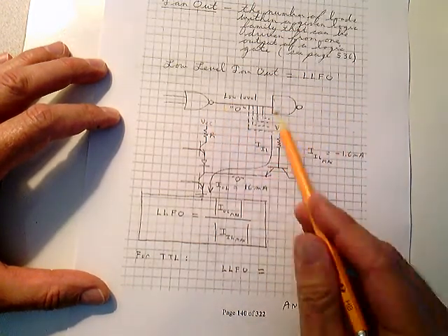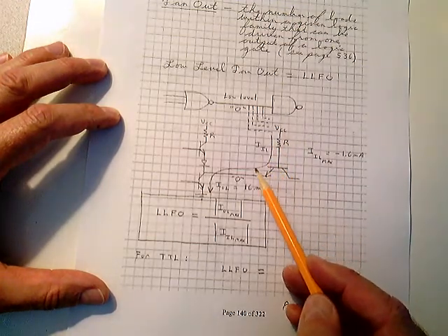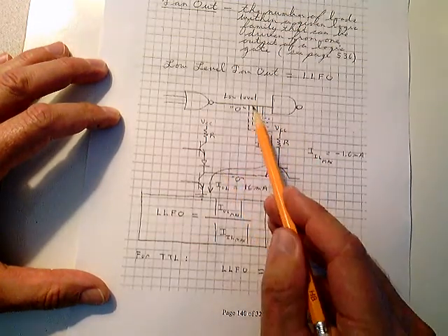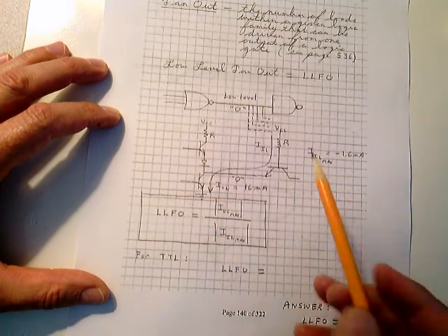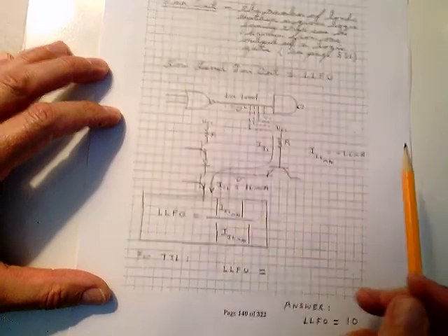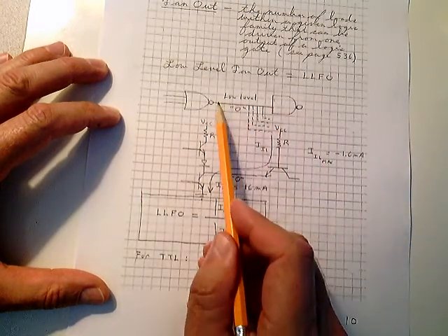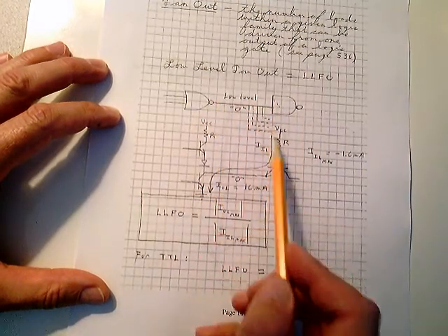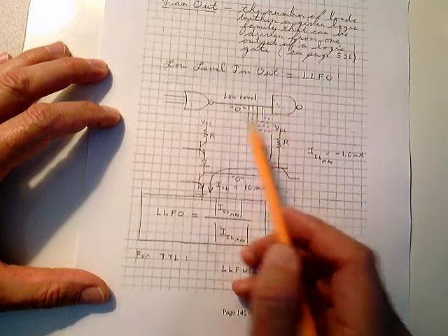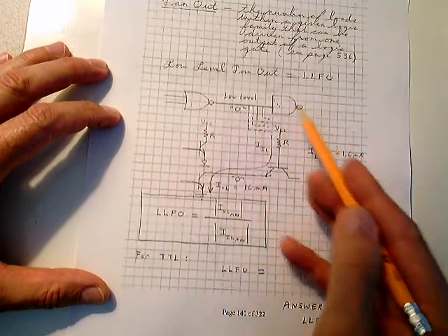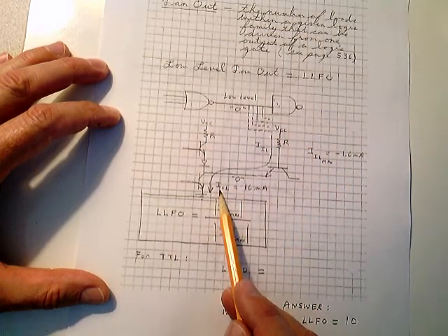What it's really doing in the integrated circuit, it's coming down here, out the multiple emitter, and it's coming over the output line, and it's going down to ground. Well, in the low state, how many of these can you tolerate? Here's 1, here's 2, here's 3 or 4 or 5. How many of those can you tolerate before you fill up, before you exceed the 16 milliamps?